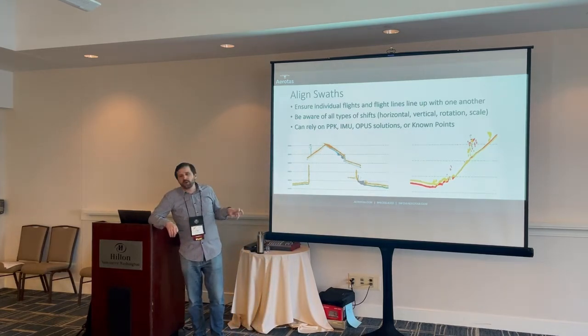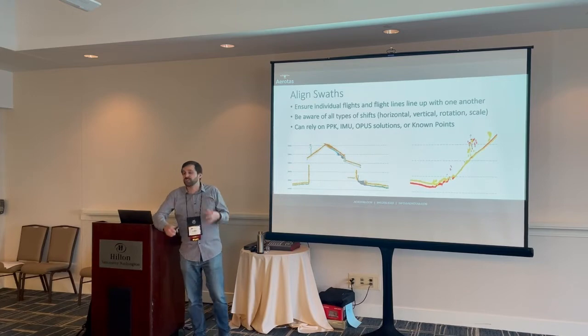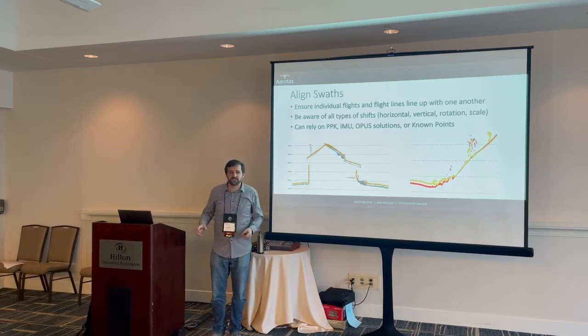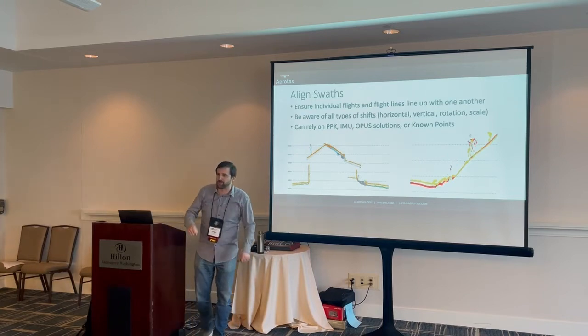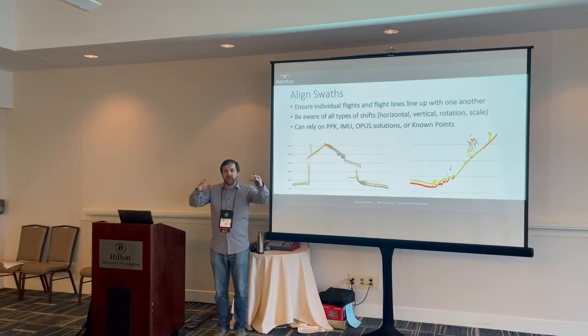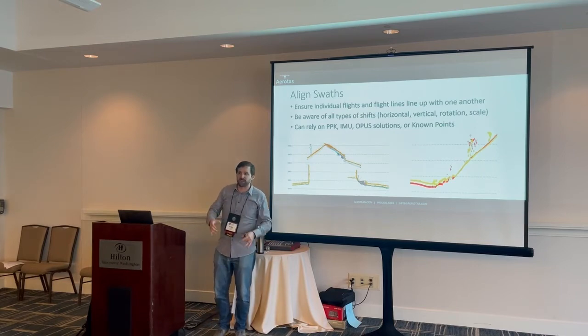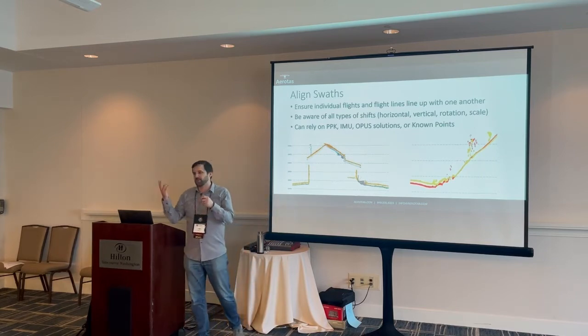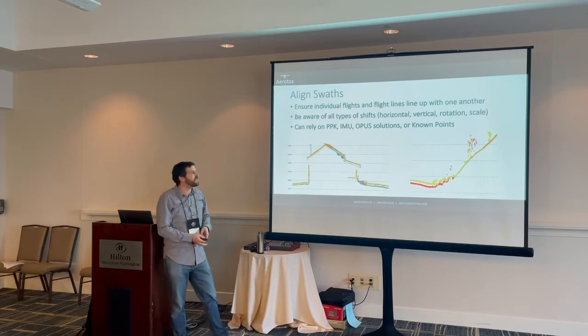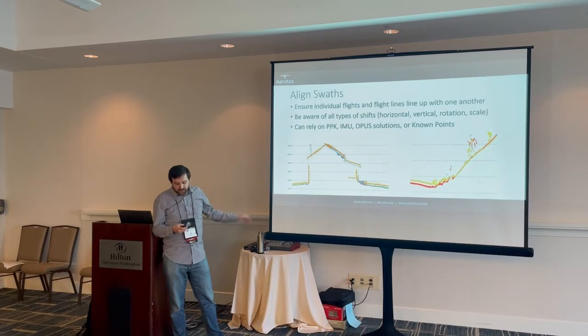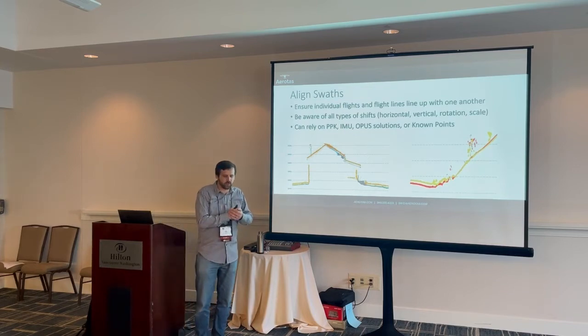each individual point cloud is going to be precise by itself. Precise meaning that any two points on that one point cloud are very good, but they're very often not accurate, which means that that point cloud is not accurate within the world perfectly. It might need to be shifted by sometimes as little as a few tenths, sometimes nothing at all, and sometimes as much as a couple of feet. But it's very common to be able to shift these in some sort of LiDAR processing software.